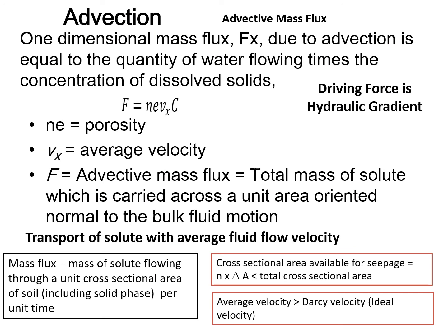Now there is something about the mass flux, and it is actually a change. Flux is anything which is changing with time and with location, and can be associated with any kind of parameter. It can be mass flux, volumetric flux, or density flux. While talking about the movement of water in a typical direction, we can determine the flux in mass. Mass is only related to the contaminant solute. So when the solute is moving along with water, how can we determine its flux? This is the expression.